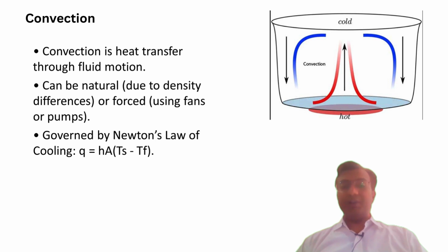Convection is governed by Newton's law of cooling, which relates the heat transfer rate Q to the surface area of the body, the temperature difference between the surface of the body and the surrounding fluid, given by Ts minus Tf, where Ts is the surface temperature of the body and Tf is the temperature of the fluid surrounding the body, and the convection heat transfer coefficient h.